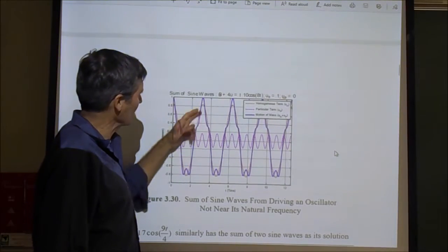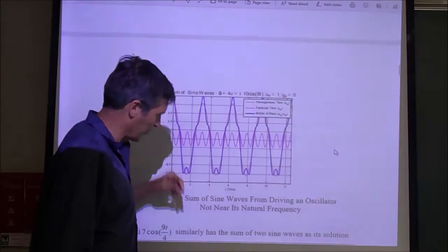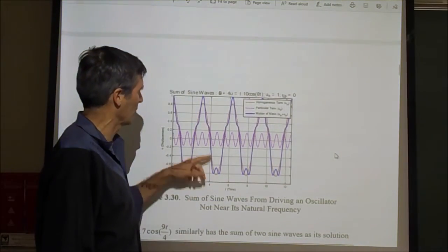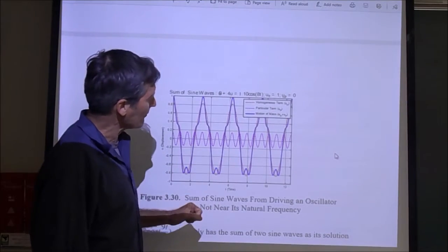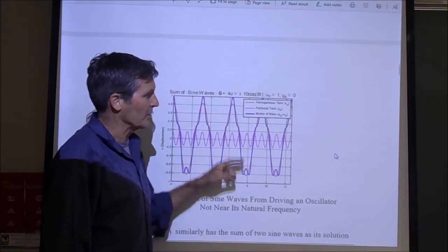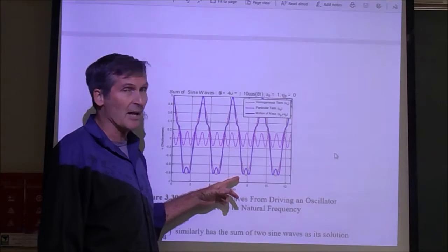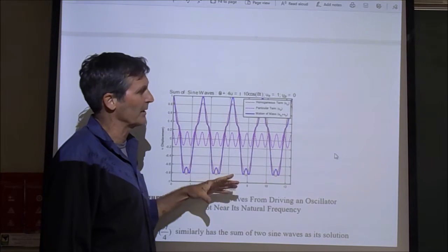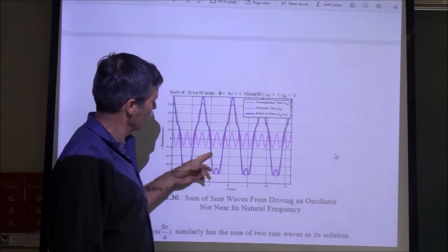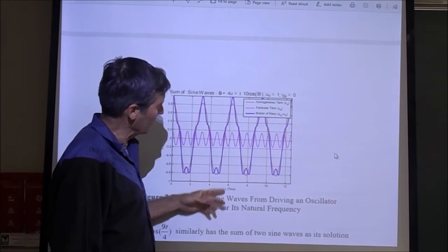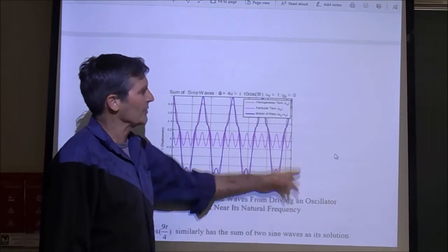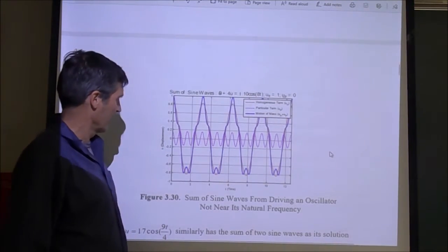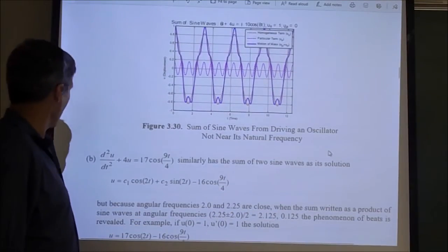If it's oscillating like this anyway, every time it comes down, I push it a little harder, and a little more, and a little more each time. There's no damping in here, right? There's no damper, it's just the mass and the spring, and we're assuming no friction. If you push a little bit more each time, it starts getting bigger and bigger oscillations, and that is called resonance.